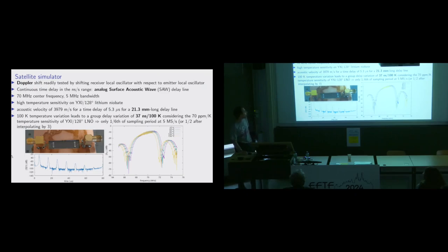If you take the time domain, you see here the 5.6 microsecond trip, and then you've got the triple transit, because this guy here is acting as a re-emitter, so you've got all the triple transits, so you've got 6, 18, 24, and so on microseconds. These are the ripples. Even though you're putting acoustic absorber here, you will still have a re-emission of the strongly coupled material. But you don't care because these are well beyond the correlation peaks that we're working on.